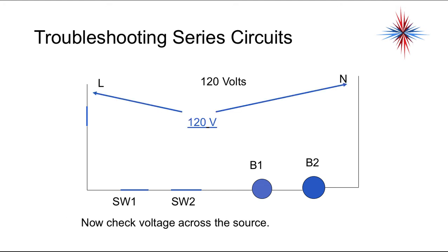Now check the voltage at the source. Make sure you have source voltage. If you don't have source voltage, don't even bother going through further. Find out why you don't have source voltage.